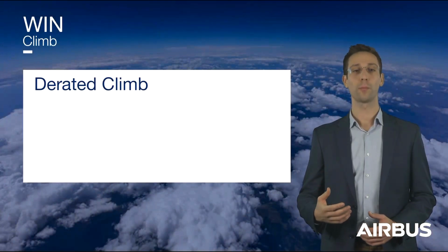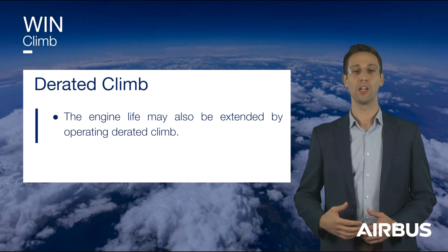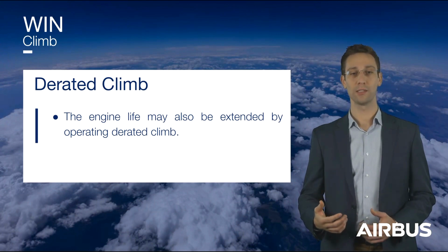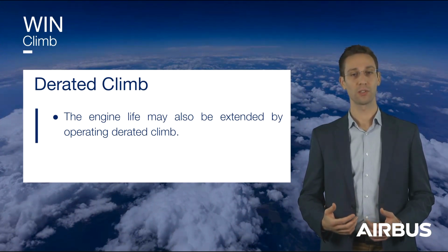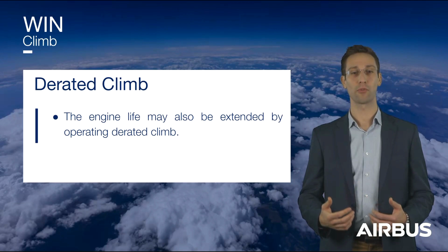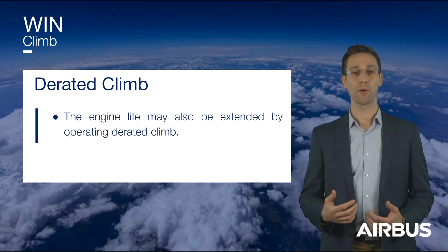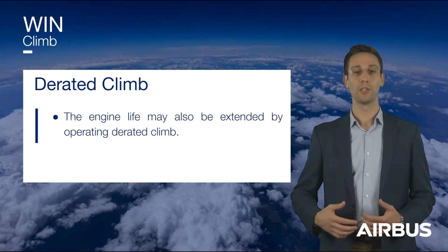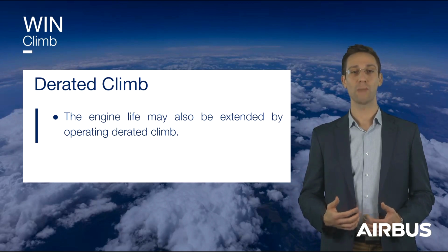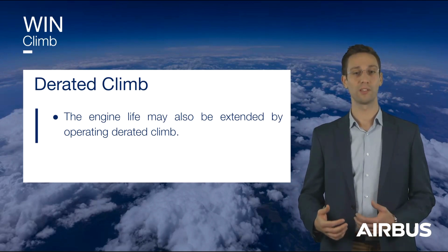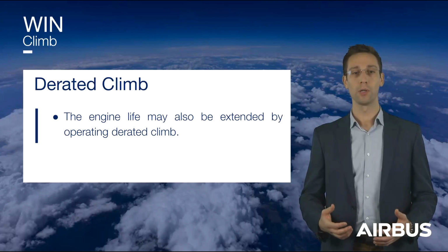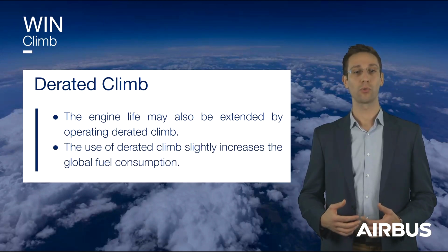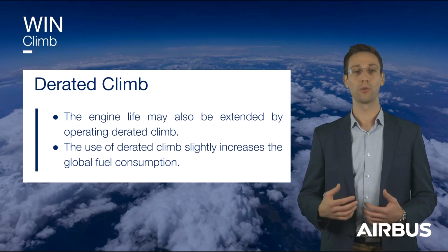Now, a few words about derated climb. The engine life may also be extended by operating the engines at less than the maximum climb thrust. Climb performance is reduced when using the derated climb thrust, but the ceiling is not affected. The derated climb increases the time and distance to the initial cruise altitude. Furthermore, the use of derated climb also slightly increases the global fuel consumption at a specific cruise altitude.